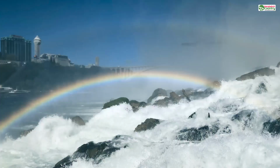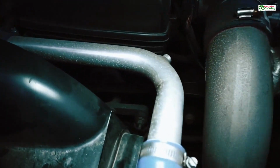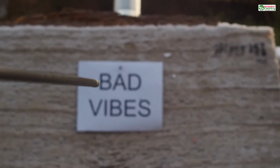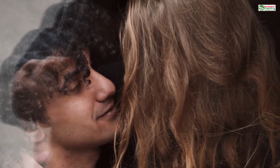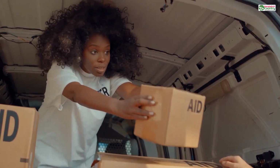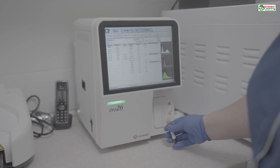The most powerful tool in your arsenal is often called Select Non-Manifold. When you run this command, the software automatically highlights every edge that's part of a leak. The edges of any holes will light up like a neon sign. Any faces that are connected improperly will be flagged. This command doesn't fix anything, but it does something even more important. It gives you a precise, undeniable map of every single problem in your model. It's the diagnostic tool that tells you exactly where the digital surgery needs to happen.